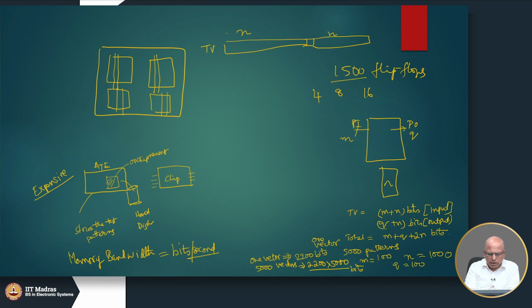And the number of scan chains that they feed can vary from 1, 2, 4, 8, 16, 32 and so on. Some people call them scan channels, and it can be 1, 2, 4, 8 etc. It may go up to 32 or something like that. The higher end testers will have more scan channels. The low end testers will have a fewer number of scan channels.